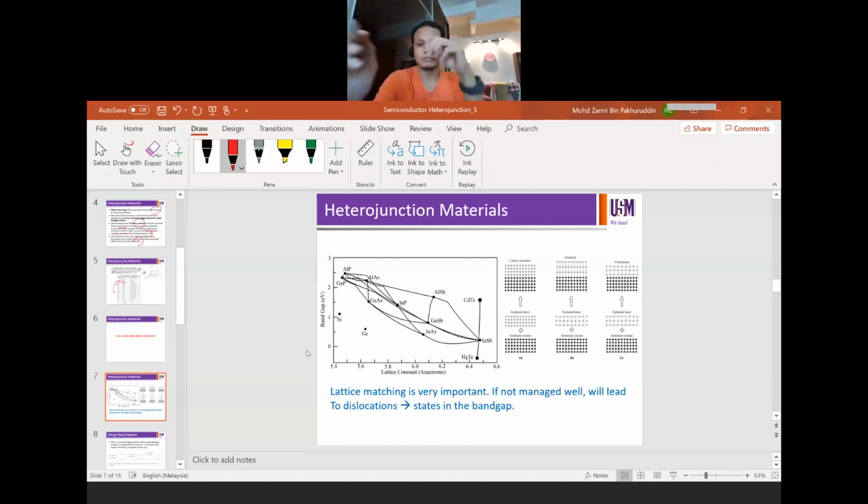If you look at this schematic representation on the right hand side, we normally have to deposit our layer on the underlying layer for various applications. For example, if you're talking about an epitaxial layer, the epi layer we normally use in LEDs, lasers, detectors, in which you deposit a very thin layer on a particular substrate, and that substrate can be a semiconductor material, or it can in fact be an insulator as well.